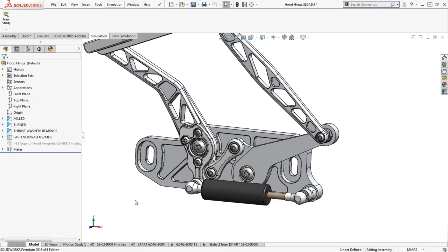But what I would suggest, if you are planning to use the tool, is to still run the analysis on the initial design space model. Because to me, it doesn't really make sense to optimize a part or a body if it's already failing your design constraints off that initial design. If it's already not meeting your criteria, why am I going to optimize something if I'm going in a bad direction and maybe wasting time in the long run?